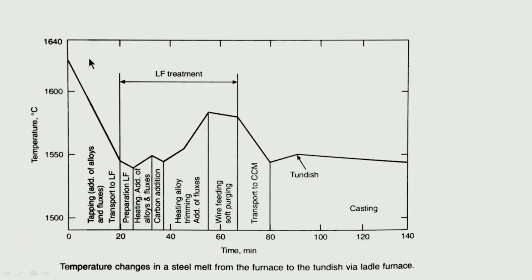In the process, the extent of dephosphorization is relatively less if you have more temperature here. So now what is going to happen? We are tapping it and we are adding the alloying elements. All these will cause the temperature to come down by, say, about maybe 70-80 degrees centigrade.